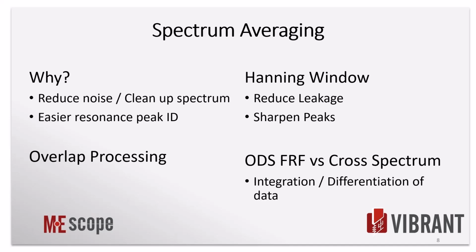But you're going to look at the FFT data ahead of time, prior to averaging, and then you do your spectrum averaging with your overlap processing. You look at it after, and it's considerably cleaner, just a much more usable form of data at that point.